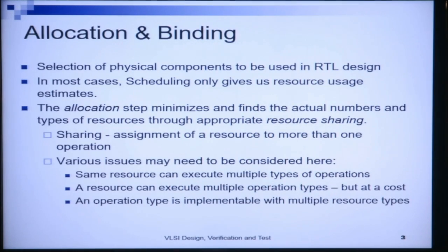Now, after we have assigned a time step to each operation, our job is to actually allocate and bind physical components to the RTL transfers. To the operations, we need to assign functional units. To the temporary registers, we need to assign actual hardware resource registers.